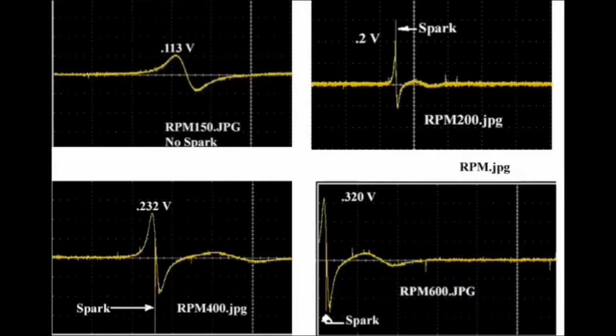Now the spark may be added to the computed voltage for the pulse. That doesn't seem to be a problem if there's a negative going pulse, but for the positive going pulse here, it seems like it is. It's also a very low RPM for getting an advanced spark, so I have no idea what I set the air gap at, but it obviously needs to be a little bit wider.